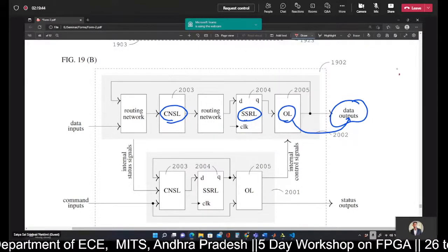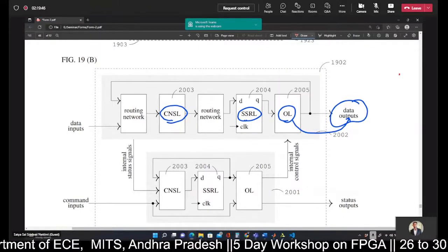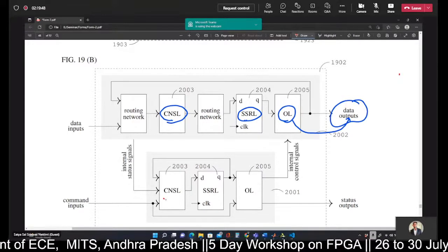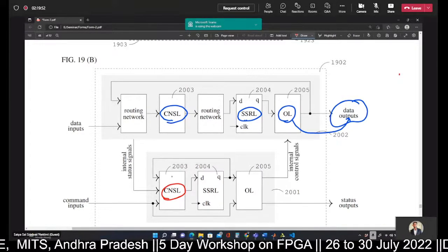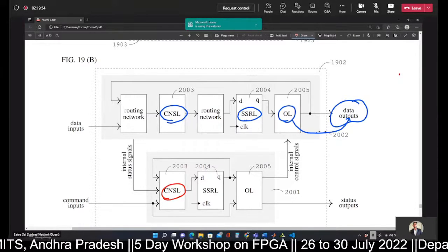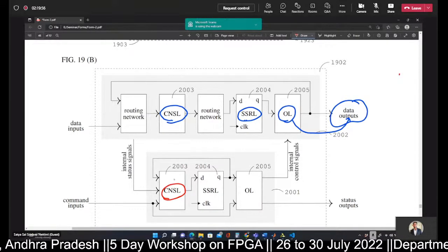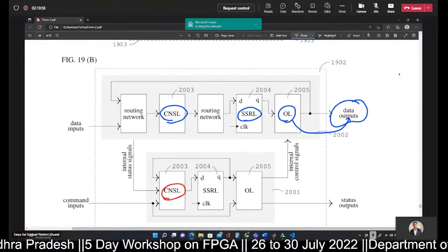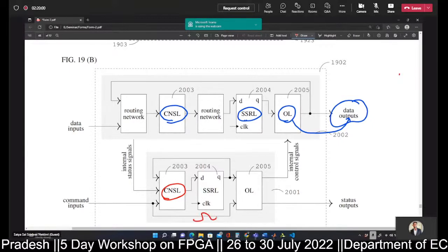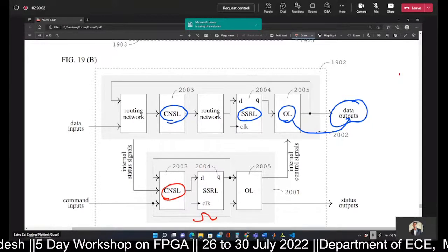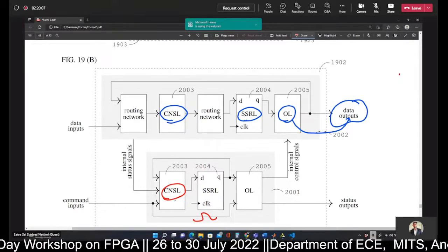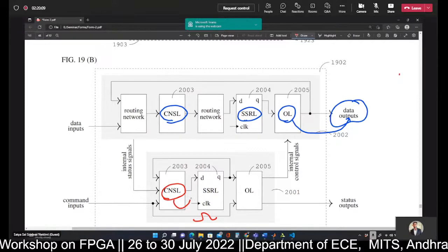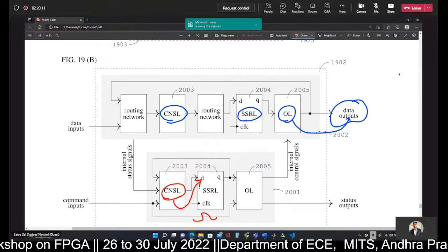If you made the start signal high, immediately the combinational next state logic will calculate that the next state has to jump to S1, and also ready should be equal to 0. Then on arrival of a clock edge, the FSM makes a transition into S1 state. Why? Because the combinational next state logic value is being updated into the register.